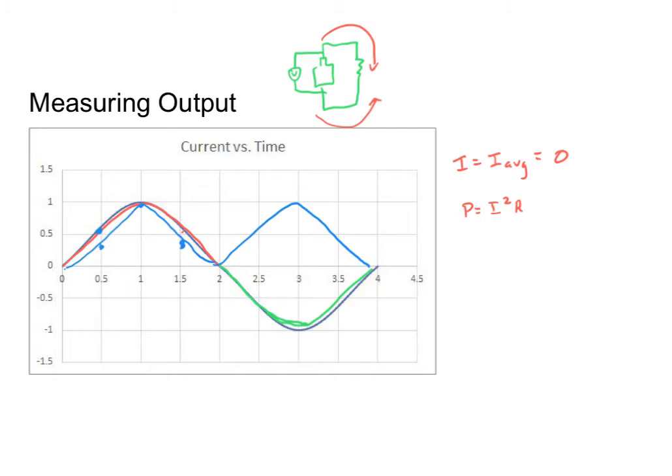And so now it's actually useful to measure the average value of our power. In doing so, we will get the measurement of the strength of our alternating current generator. And so we're getting a really useful value that helps us compare one alternating current generator to another. In fact, we are going to measure our alternating current value by using the equivalent direct current that delivers the same power as the alternating current over one cycle.